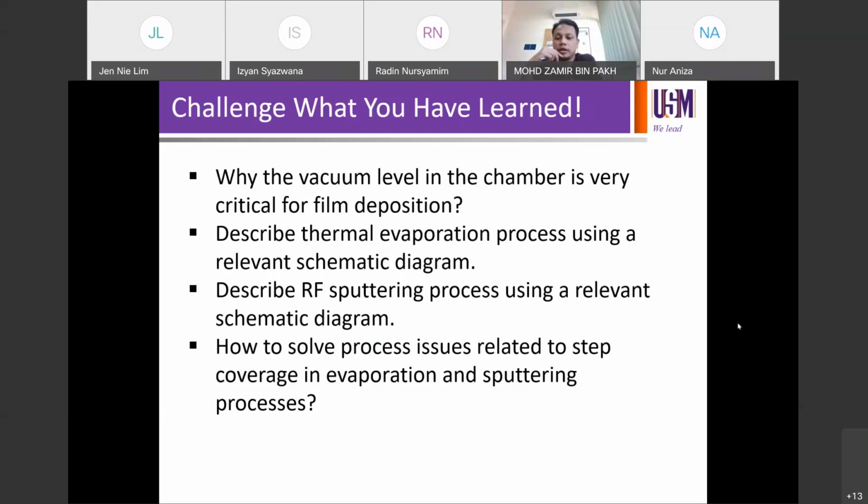Shah, yes. Good. Because we learned last time on the first few pages about the topic. You need to have enough mean free path for the particles to be deposited to travel at least from the material to the substrate for the deposition process, right? So we normally plan the vacuum level to be at least a couple of times longer than the distance, right? So you will have different mean free paths at 10 minus 3, minus 4, minus 5, down to whatever you can go. Not sure.